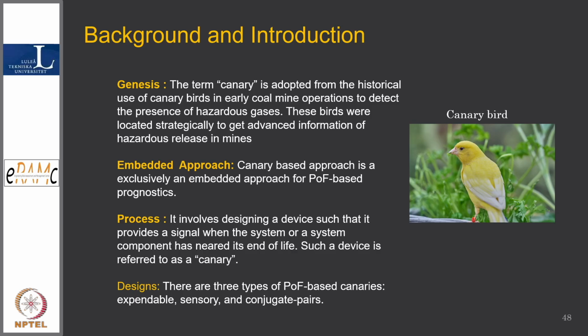Now this is basically part of an embedded approach. That means, let's say I have one component, and there are some nodes or locations on that component. I can use one as a canary, because my selected component and the other components have the same structure, and they are seeing the same operational stresses, same environmental stresses.